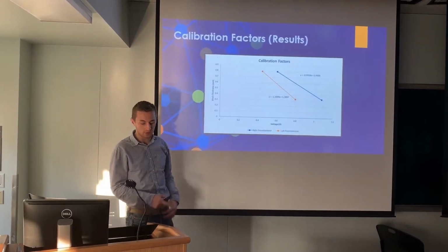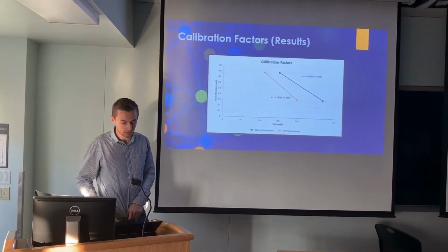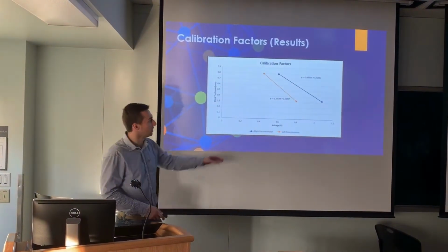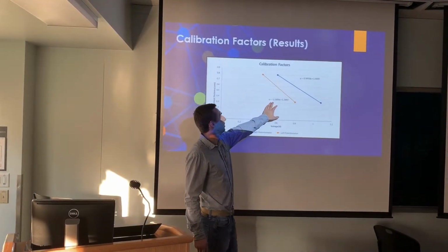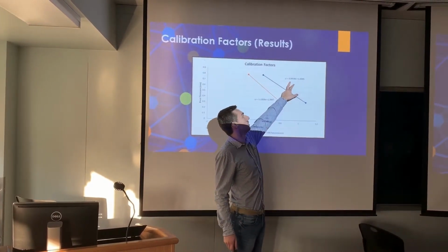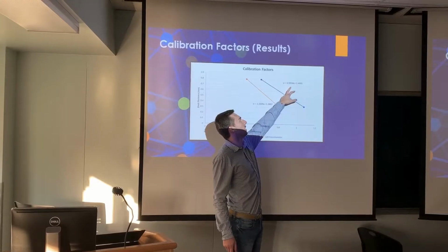You can see from this graph that it was necessary to calibrate both linear potentiometers, since one was found to be much more sensitive than the other, with a slope value of -1.33 and another one of -0.99.